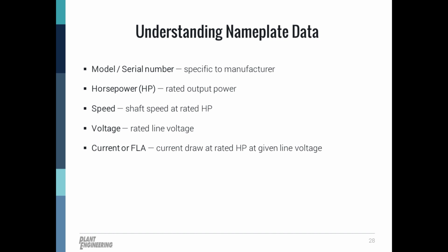I've seen many times in the past where a motor matched the basic nameplate data such as horsepower, RPM, and volts, and therefore was put in the place of a motor that was built for a specific application. A good example would be a kiln duty motor that can withstand higher temperatures, or a washdown duty motor that can withstand direct water contact. There are many motors built for specific applications and therefore make it just as important as the motor nameplate information itself.